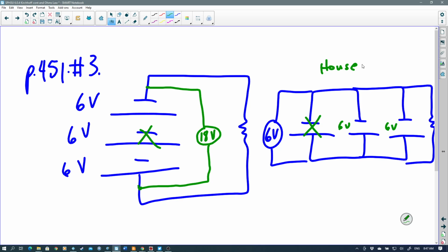If one thing goes out, like a breaker, if that disconnects a whole bunch of things that are connected in different plugs, then that's a series scenario. But if the circuit is working fine and you unplug a light, it's not all the lights that go out. Okay, so for a household, it's a little bit complicated. We'll look at that a little bit more in detail later. But generally speaking, most of your circuits in your house are parallel circuits.